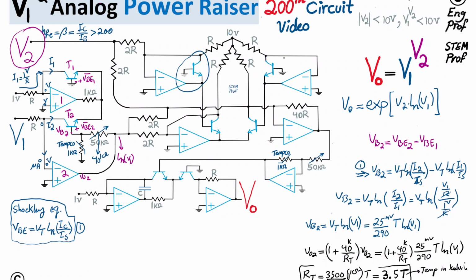Now, these 4 NPN bipolar junction transistors, or BJTs, should be matched together. They should come from the same process, on the same substrate and package, so that these 4 NPN transistors share the same process, junction, and temperature properties. With that said, let's name them transistors T3, T4, T5, and T6.